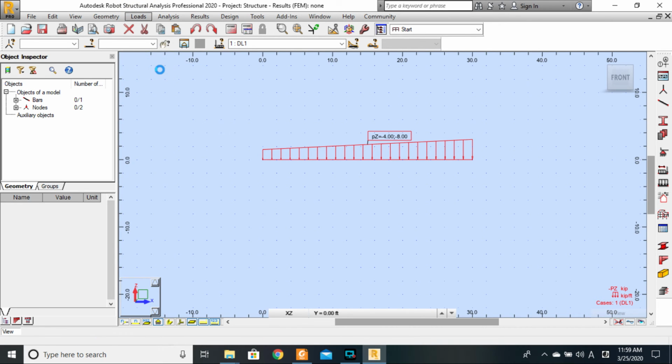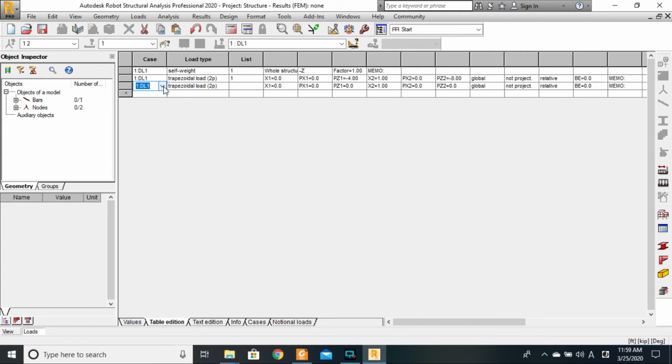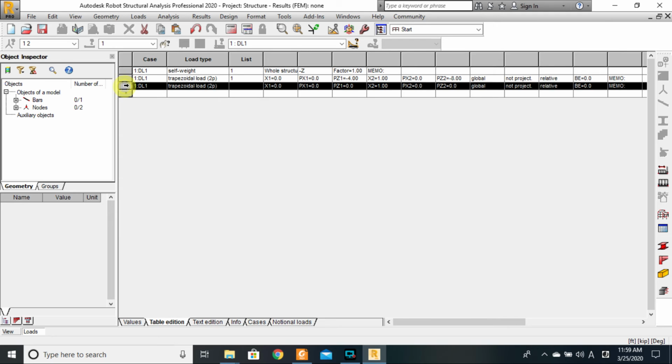Okay, load table will show you all of the loads that you have applied on the different elements. It's a kind of tabulated list of loads, right? Good. Look at this. Oh, I've just added a new load by mistake. So when I want to cancel the load here, I will just select the line. You see that? Select the row concerned and press Control X, and that should disappear.